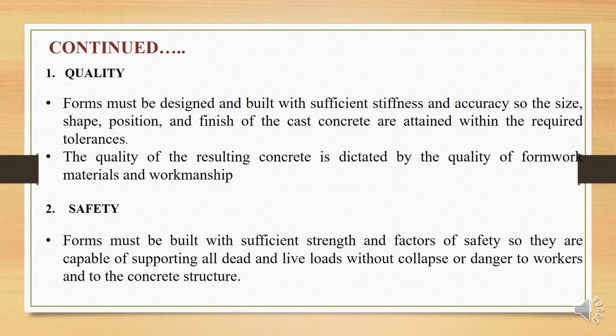The quality of formwork itself has a direct impact on safety, accidents, and failures. The quality of resulting concrete is dictated by the quality of formwork materials and workmanship. Many concrete-related problems such as discoloration, stains, and dusting are attributed to concrete formwork. Also, some deformed concrete surfaces are due to the deformed formwork system caused by repetitive reuse and inadequate support of formwork. Also, joints that are insufficiently tight will leak cement paste.